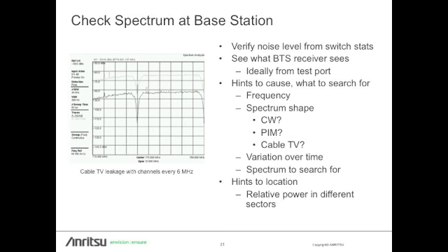So first we see that the noise level really is high. It's not a problem with the switch statistics themselves. We can see what the spectrum looks like that the base station receiver is actually seeing, ideally from a test port if you can get that.